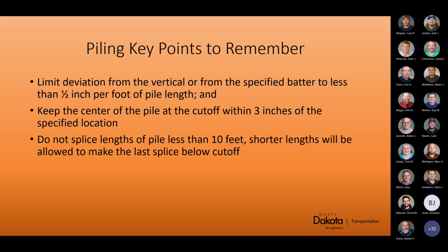And then do not splice less than 10 foot of pile on when you're driving. At the end, if you get a 50-foot stick in and you need to add 2 feet to do your cutoff, that's fine. It's allowed, but you just don't want to be adding less than 10 feet in the spec book. And like I said earlier, and in my notes here, you'll get grease on everything. So just be aware of that. Them hammers are extremely dirty.